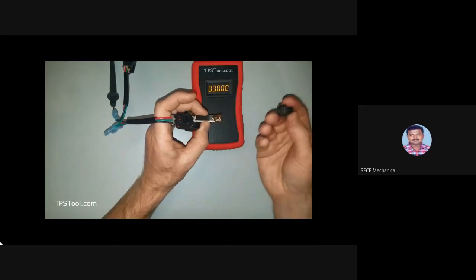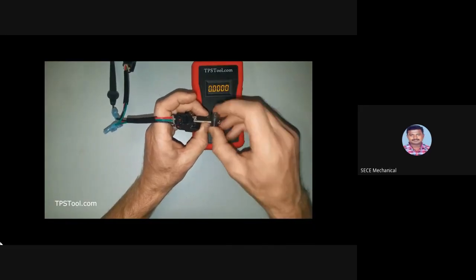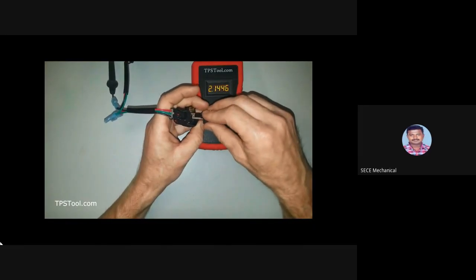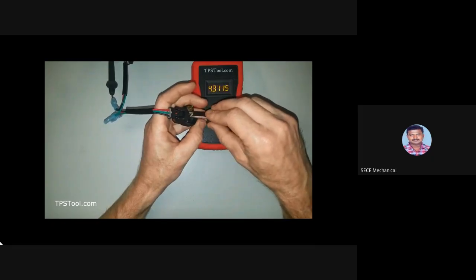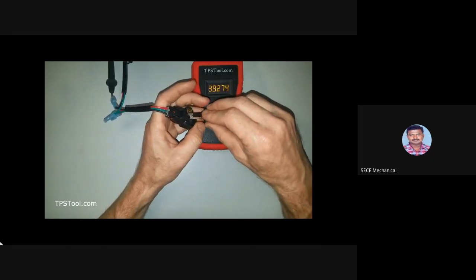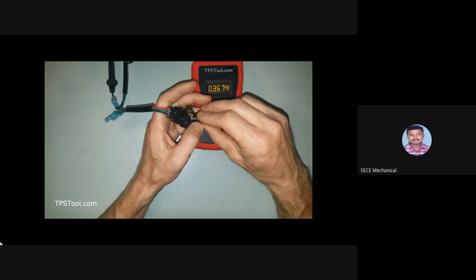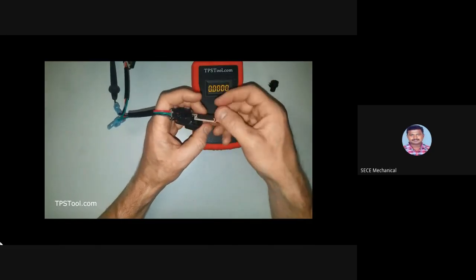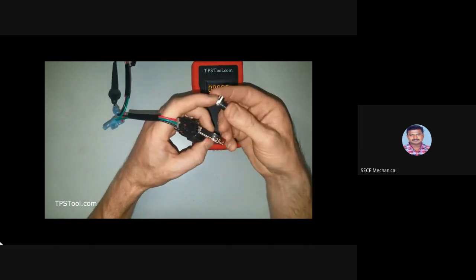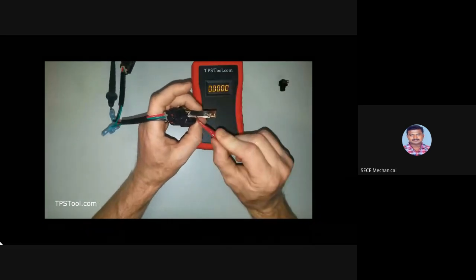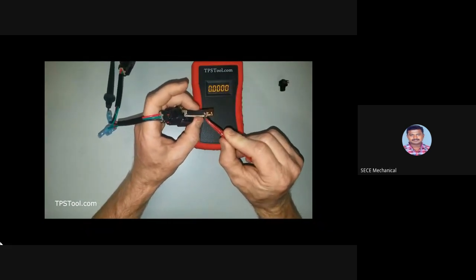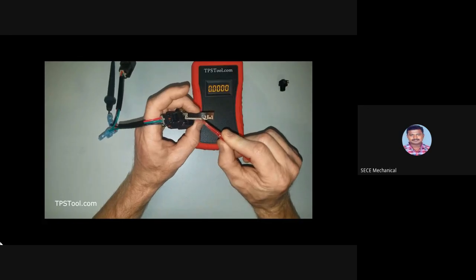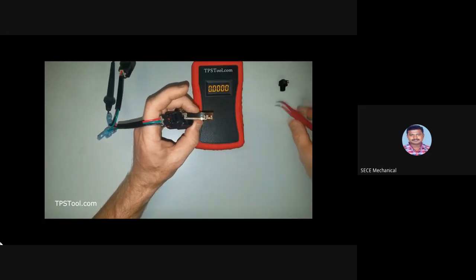So we'll take our wiper here and see if we can do this manually. My fingers aren't too fat to be in there. So there we go. And as we slide it across, there we go. We slide it back down the aisle, right? So when a TPS goes bad, usually what happens is one of these wipers, something will happen to it, or something along this conductor will either get worn out and chip off, or maybe it'll get some dirt in there and it won't conduct all the time. You know, these wipers will touch the dirt and they won't make good contact or something like that.